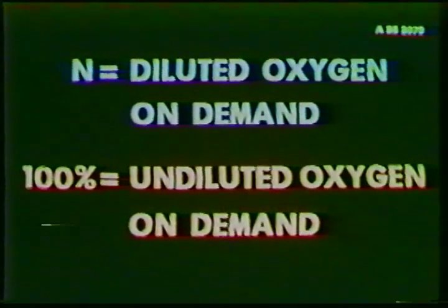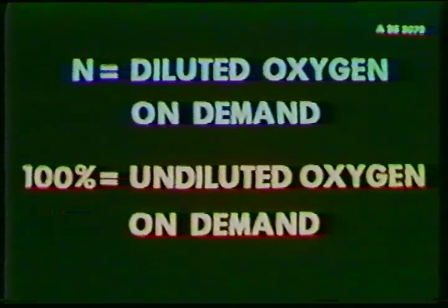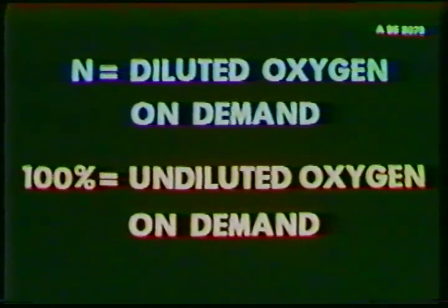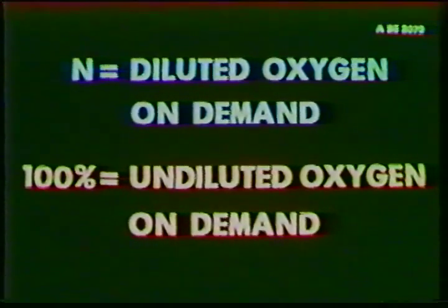A manually operated normal 100% control has been provided on the mask to select 2 supply modes. N for normal gives diluted oxygen on demand. The 100% position gives pure oxygen on demand.